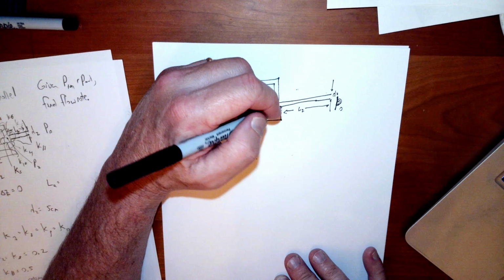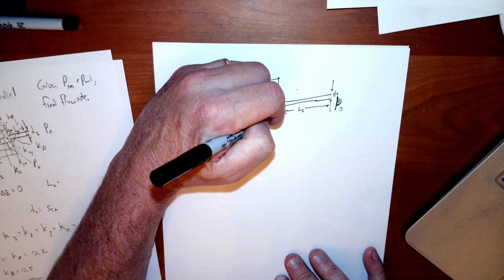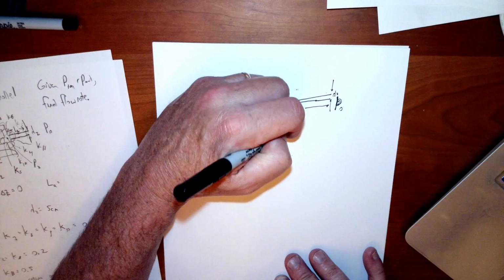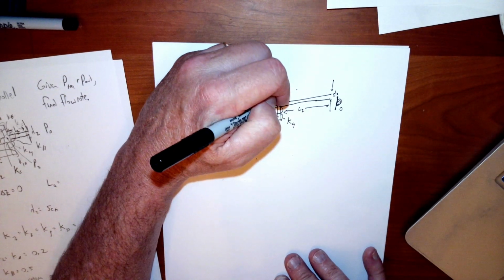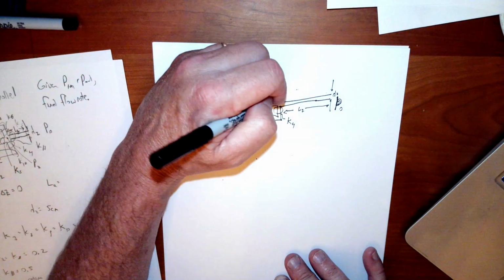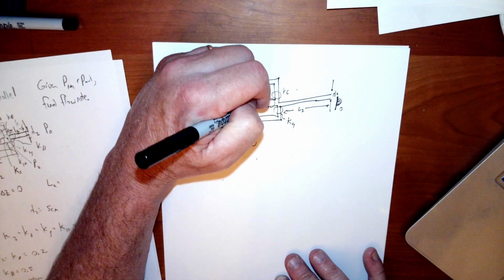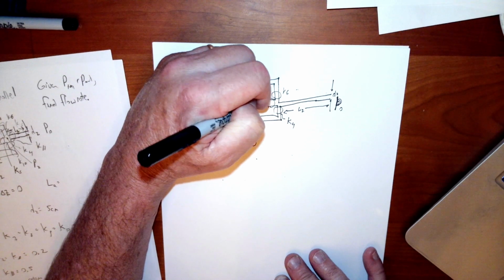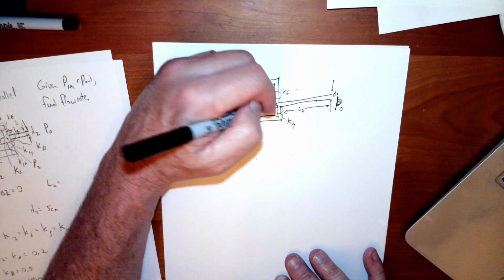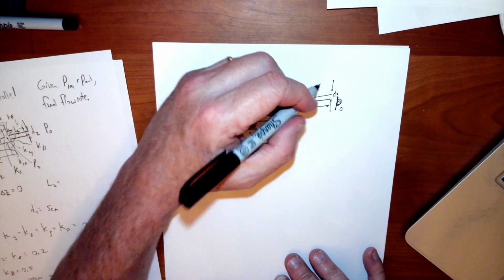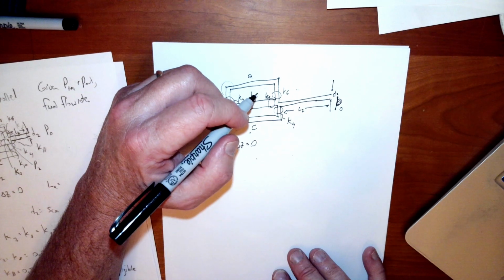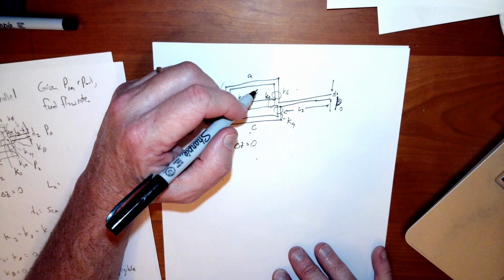Before we do the corners, let's do the same thing over here. Sorry, just keep my numbering scheme the same as I had. So where it's entering the junction here is going to be K4. Entering the junction here could be K6. And entering the junction here could be K5. Again, there could be recirculation zones as they go past these sharp corners, causing losses. There's of course going to be all the corners now, right? These sharp corners are all going to have significant losses.